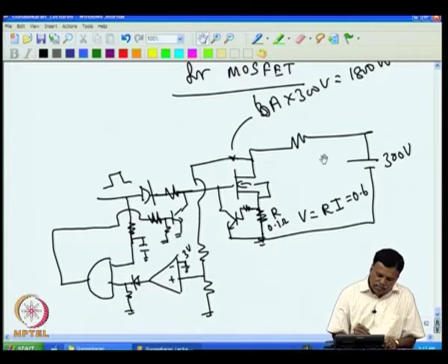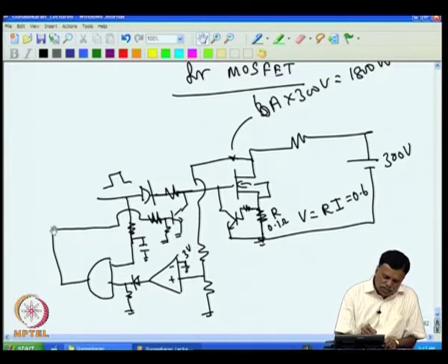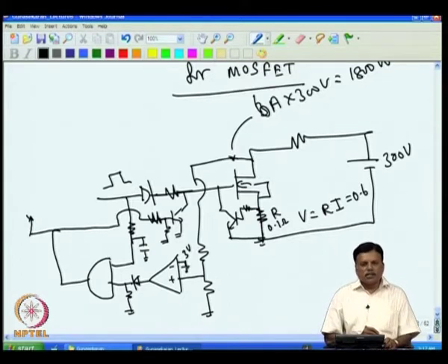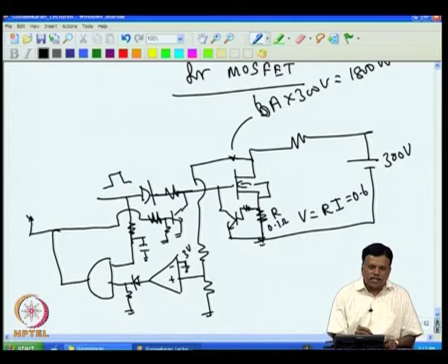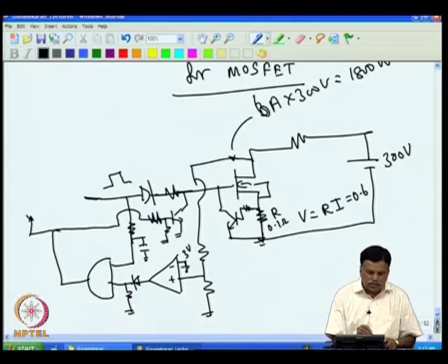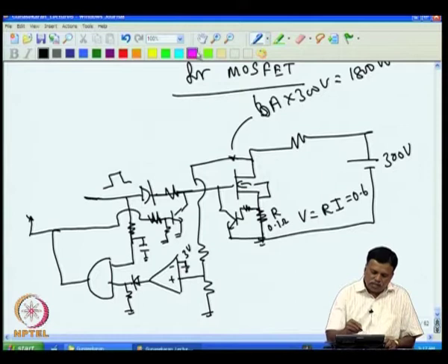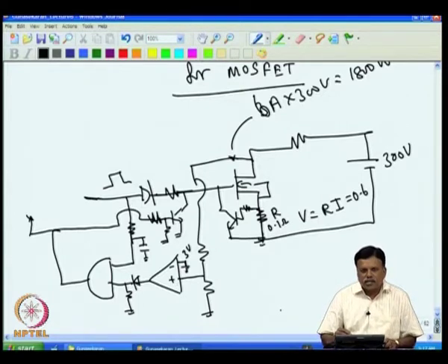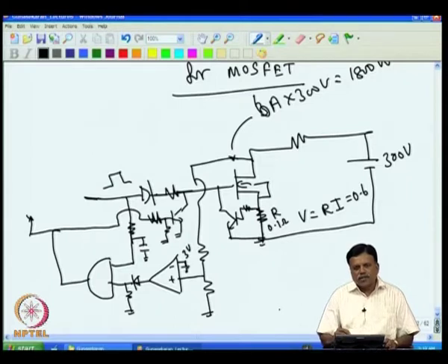So, this latched information should go to the controller, so that the controller can make sure that the latch is removed frequently, once in a while. That arrangement can be done, for example, we can switch this signal on and off once in a while, so that once the short is removed, the current conducts and it works. So, you can think over this issue and see what best can be done, or even this circuit can be modified such that automatic recovery is also possible. This I leave to you as an exercise.